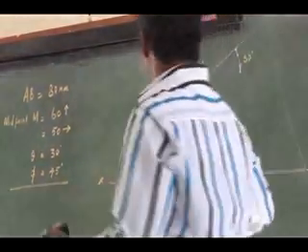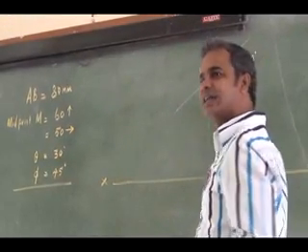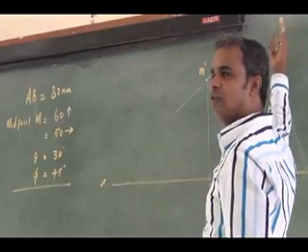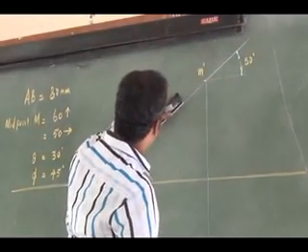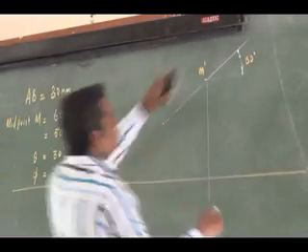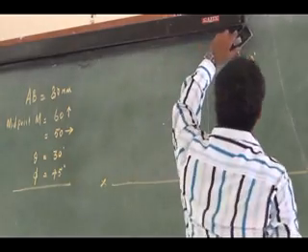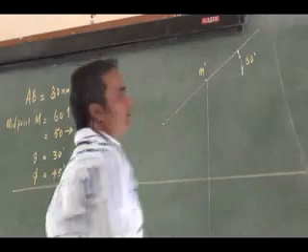40 mm. It is true length I have to measure it here. 40 mm, okay, this side and 40 mm the other side of the midpoint projection, right? So 40 mm I have to measure it here. So I will have the true length. So similarly 40 mm the other side I will have the true length.